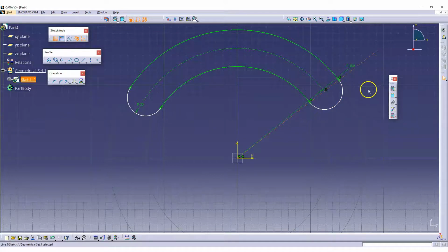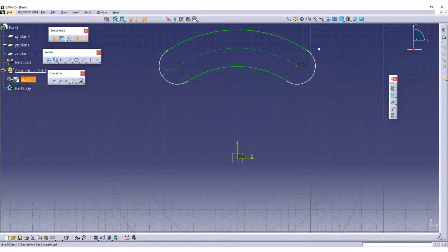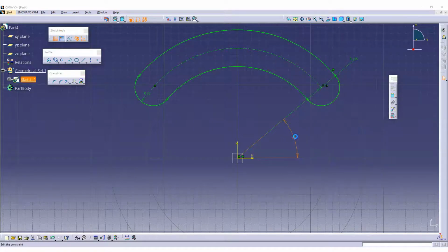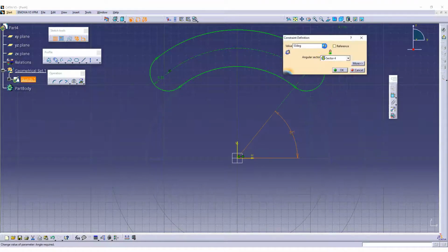Right. So now, the moment I move this one, that also is not moving. See, this is not moving. So what I'm going to do, select this point, and with control select this particular point, and then make this a vertical axis and go for constraint definition box and give symmetry. You get this one. And the moment you move this one, see that, now you can see the constraint is happening and this profile is happening. Now you know how to give the dimension between this one and this one. So these are some of the things which you need to know, how to give constraint 40 degree. So now you just keep moving this one. Because of the symmetry, whatever you have created, it happens. See this, that's a point which you need to understand.